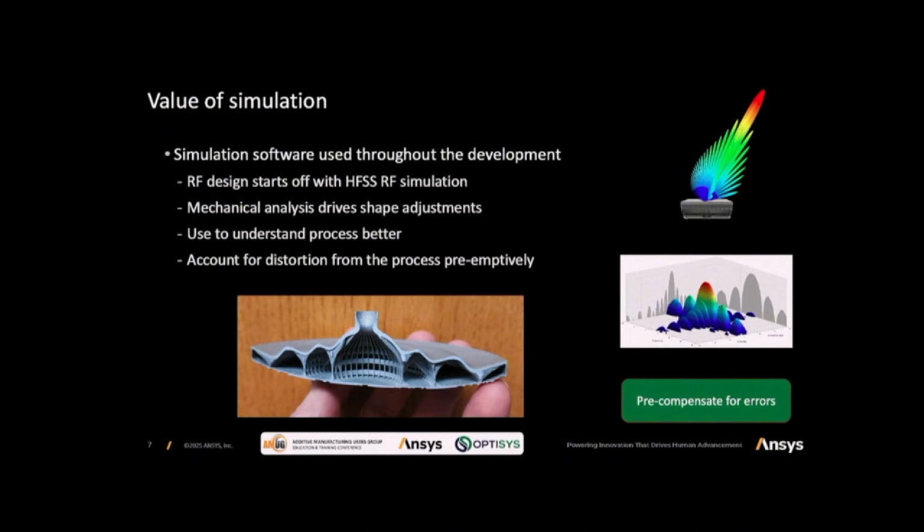You can also take that to the next level and consider manufacturing with that. In their case, they're using additive manufacturing. You can put those constraints into the meta model and come up with a truly optimized design. And then we can also avoid some of the waste that happens oftentimes. Anybody that's involved with metal additive manufacturing knows there are times where you run into issues. You may have a recoater interference issue. You may end up getting distortion in your part. You may end up with other problems.